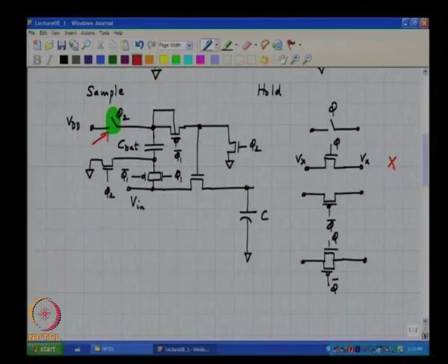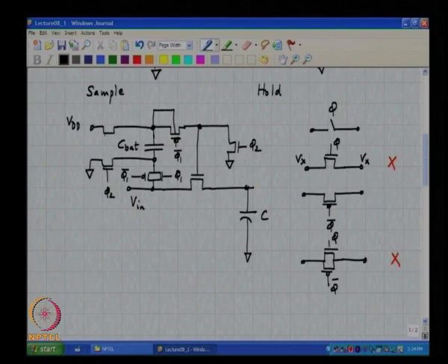The potential is too high. So, NMOS is not helping. If the NMOS is not helping, the transmission gate can hardly be used, right. So, it seems like PMOS is the only candidate which even remotely fits the job description, right. So, okay, now let us try and see if PMOS works. And what would you connect the gate to? Phi 2 bar, right. Okay.